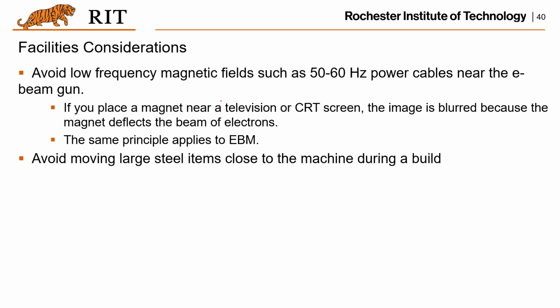For the facility of the EBM machine, because it utilizes the electrical magnetic field to control the electron beam, you do not want to have a magnetic field affect the EBM process. So that's why you always want to control the magnetic field around this machine.